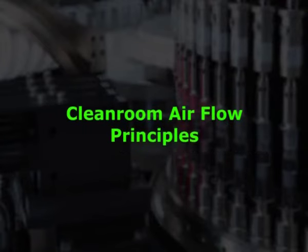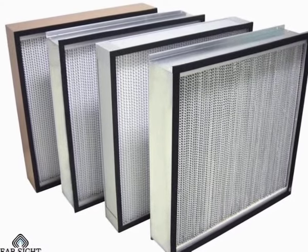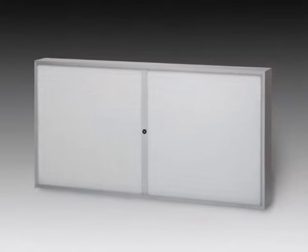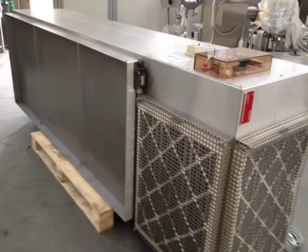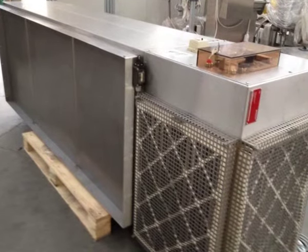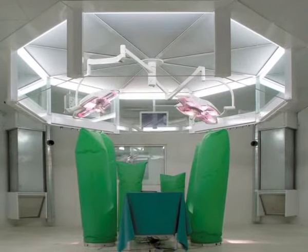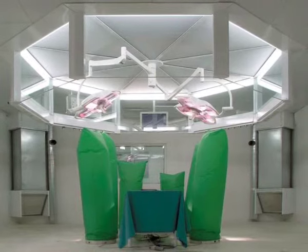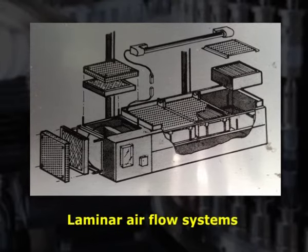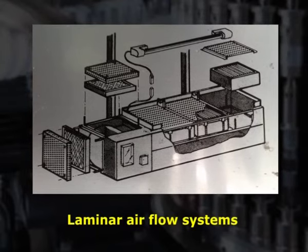Clean room airflow principles. Clean rooms maintain particulate-free air through the use of either HEPA or ULPA filters, employing laminar or turbulent airflow principles. Laminar or unidirectional airflow systems direct the filtered air downward in a constant stream. The laminar airflow systems are typically employed across 100% of the ceiling to maintain constant unidirectional flow. Laminar flow criteria is generally stated in portable workstations, the LF hoods, and is mandated in ISO 1 through ISO 4 classified clean rooms.